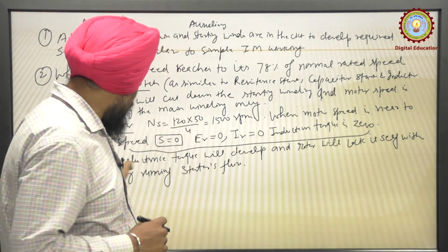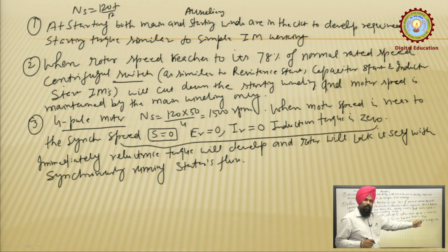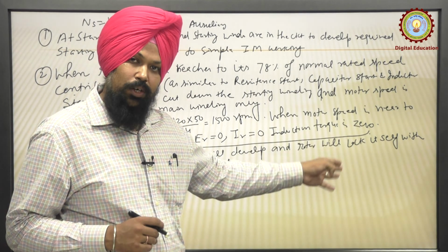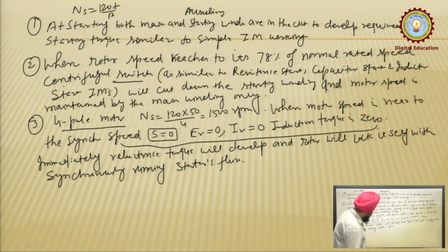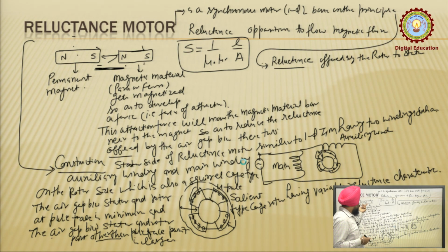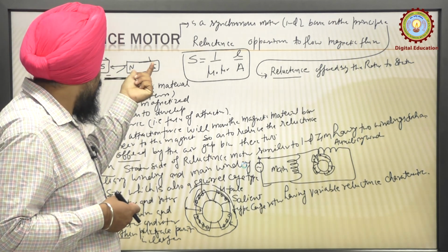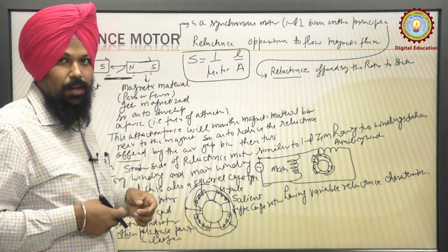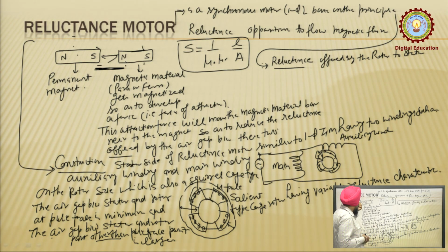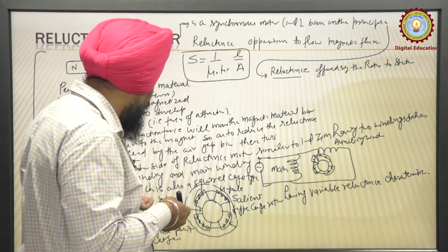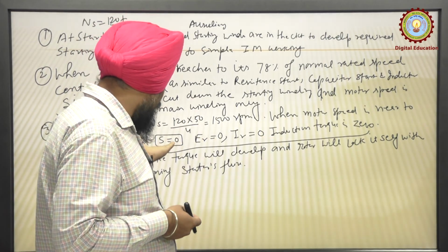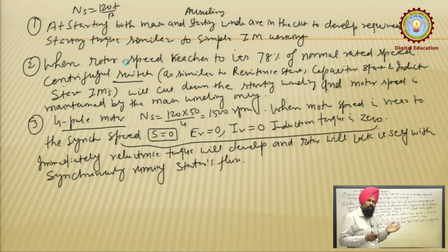Okay. This is just because of the variable reluctance offered by the rotor circuit, the rotor position with respect to the stator. As I have already told in the previous slide, by following this concept, the rotor wants to catch up the speed. This synchronously moving flux will attract this iron piece in such a way so as to reduce the reluctance. And in our case, when there is no induced voltage and IR is 0, there is no rotor flux.